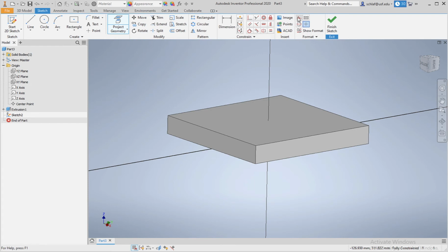And this I do with a construction line. So here you turn on construction lines, and so I select this corner, and you see now it made me here this dotted line in my sketch, which coincides with the top of this base. So this is a very important feature here, project geometry, when you start using Inventor and make drawings.